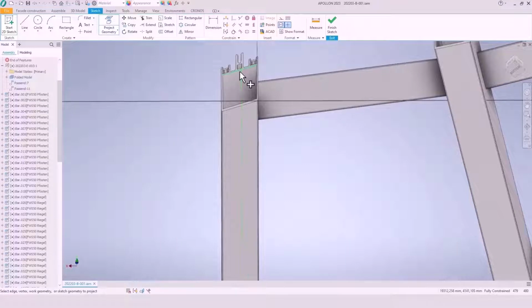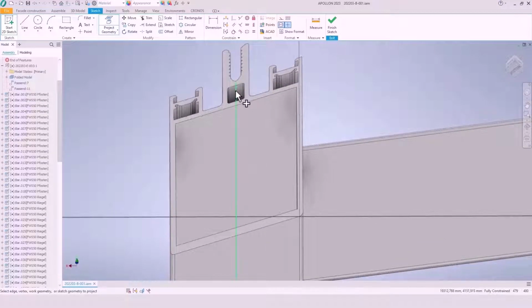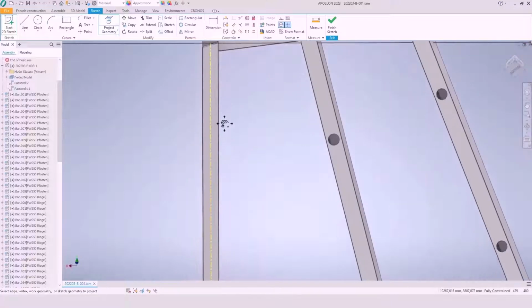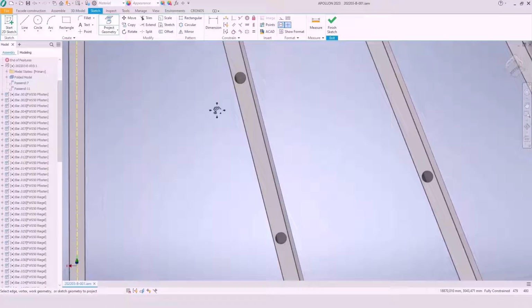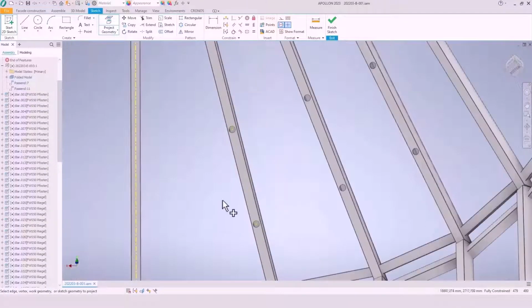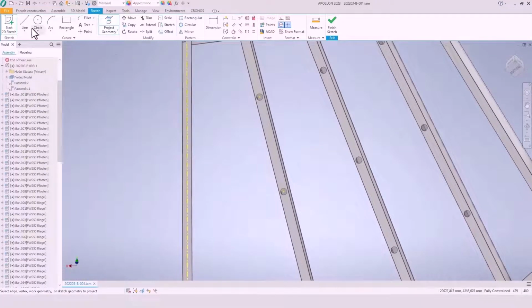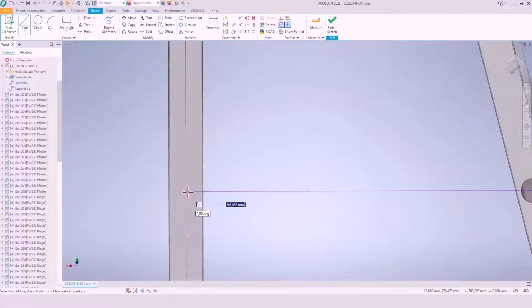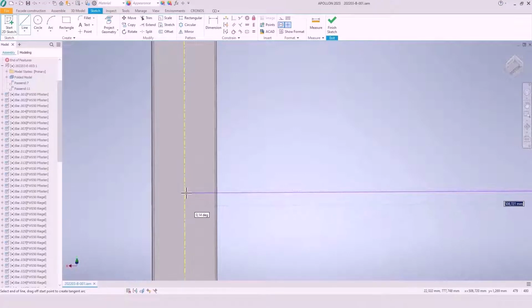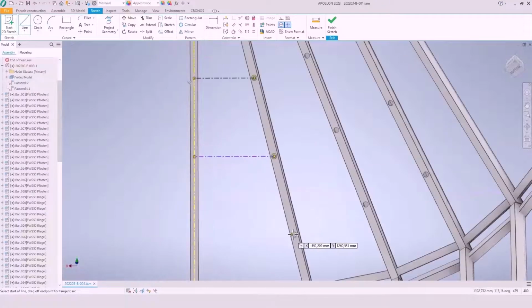And now you can project lines and shapes and points of the profile onto the surface as I did. In this case, the holes should be orthogonal to the holes of the right profile. Okay, so let's insert lines here orthogonal to the right profile and to the point of the left profile.